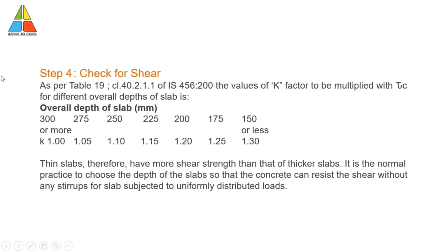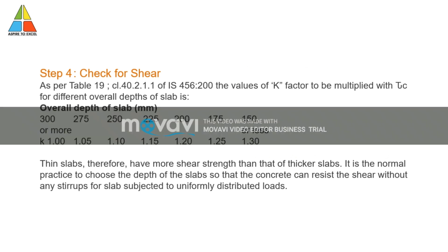So now the next step is check for shear. Generally slabs are safe against shear, but still we need to check it, because any flexural member we design to resist bending and we check it against shear and deflection.